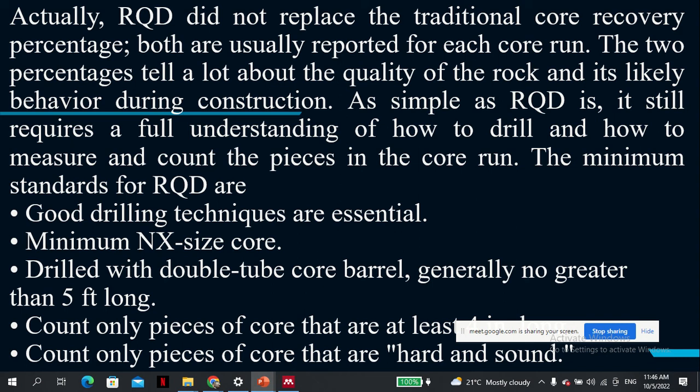versus the length of core drilled. So they are related, but RQD speaks to the length of each piece. If you consider 1 meter, how many 4-inch lengths can you recover, and those less than 4 inches. Total core recovery is, in one meter, you have recovered maybe 80 centimeters, so the total core recovery would be 80%.